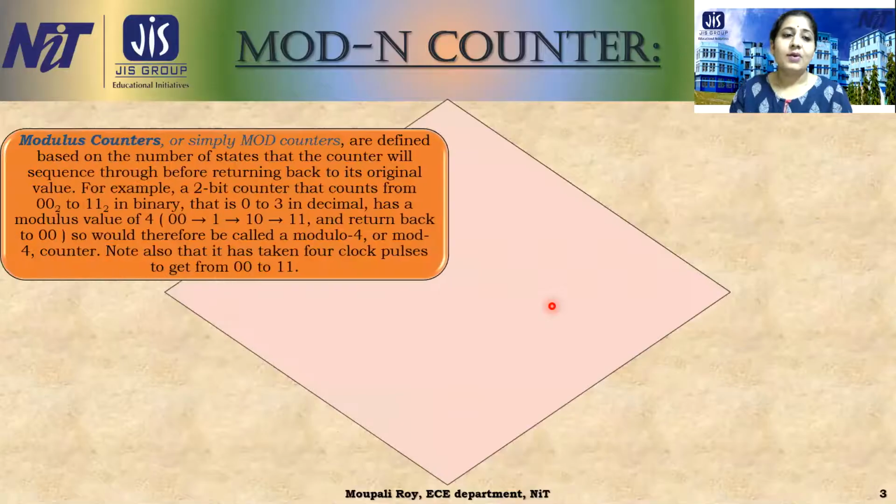So the modulus counters, or simply mod counters, are defined based on the number of states that the counter will sequence through before returning back to its original value. For example, we can say a 2-bit counter counts from 00 to 11.